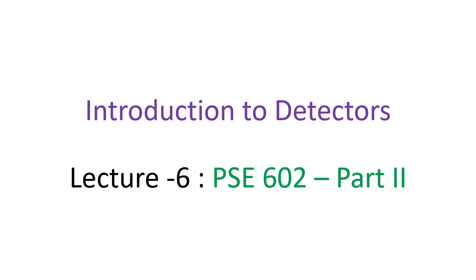That would mean that the resistance of such a device would actually change in the presence of the external photon flux. And that proportionality with the input flux and the corresponding change in the resistance is how the detection process happens.